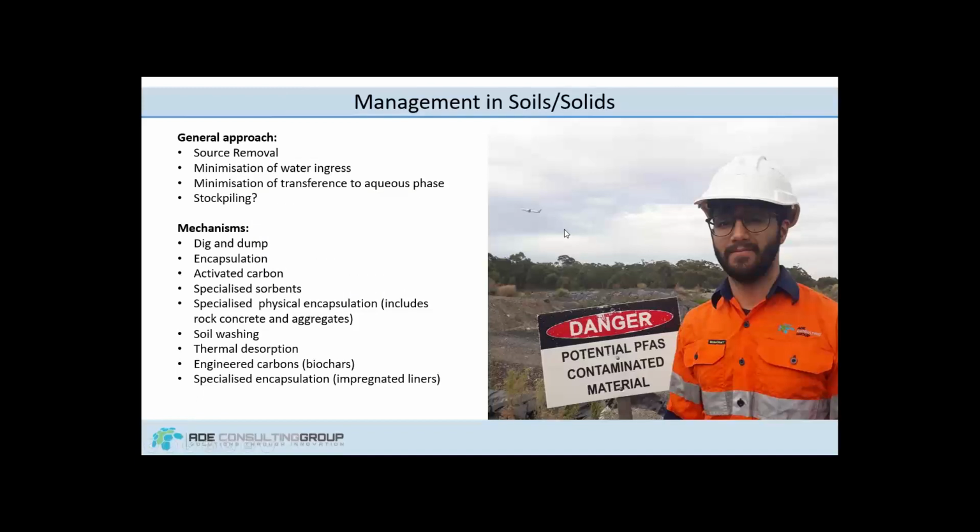So management in soils, the general approach, as we've covered, includes source removal or minimization of water ingress through the site. This can be sealing a surface, or minimization of transference to the aqueous phase. This can be the use of sorbents and other materials, mixing them into the soil to stop PFAS being transported out of the soil and into the aqueous phase, where it can be transported off-site to sensitive receptors.